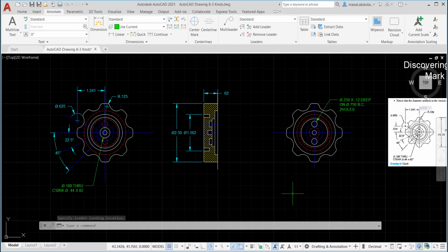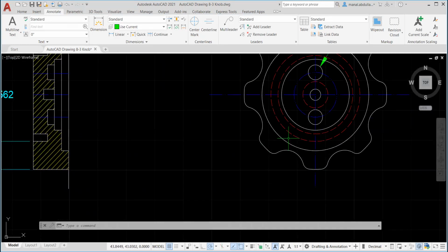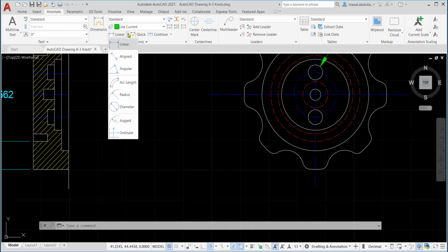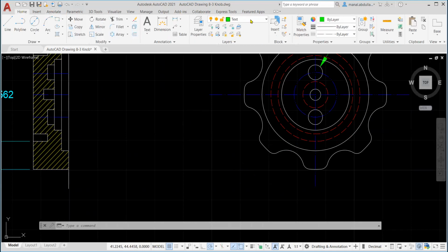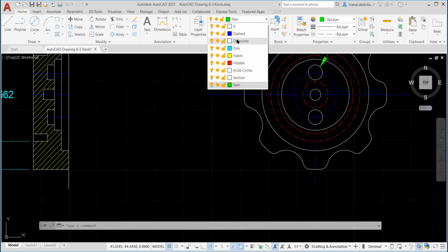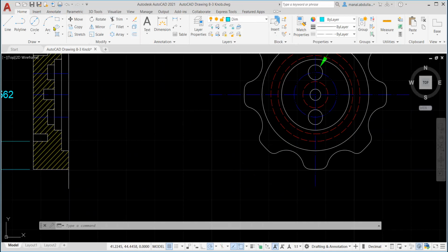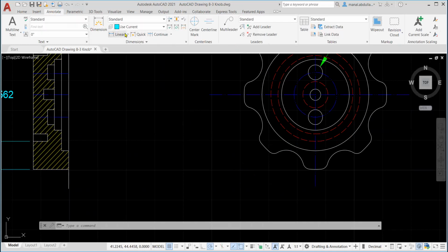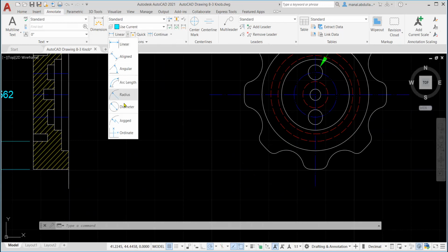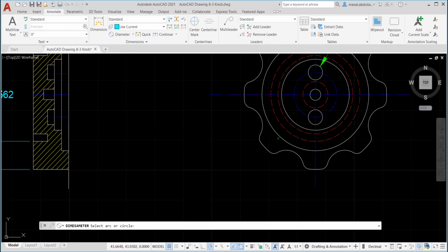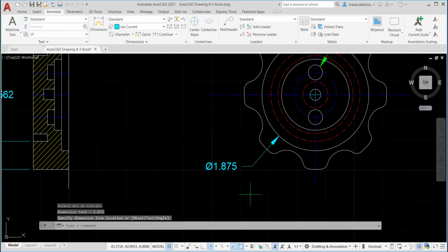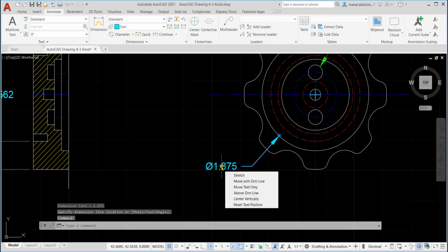As you see here, the last thing, the diameter, is just a dimension. So you can go back to the dimensions and you get that automatically, the dim layer, and annotate. And here you have the diameter. You click on that. Now remember that when you click on each diameter, you have a grip. When it's hot, it's red.